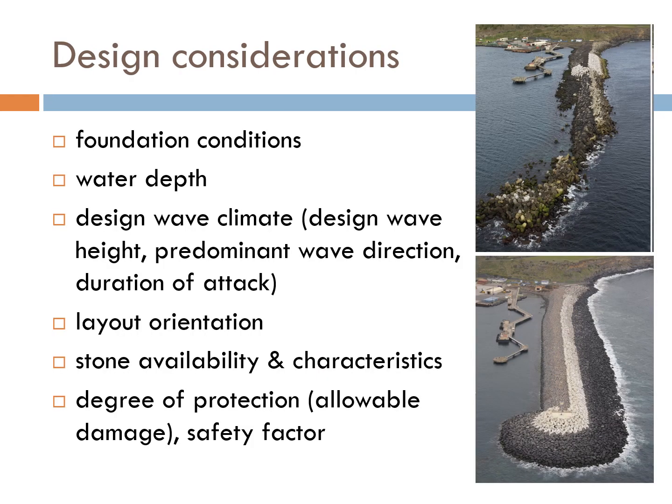Based on our previous discussion, it may thus be concluded that foundation conditions is one of the most important criteria in rubble mound structure design. This is closely related to the water depth, whereby the larger the water depth, the larger the size of the structure, and thus the more critical the foundation bearing capacity is.